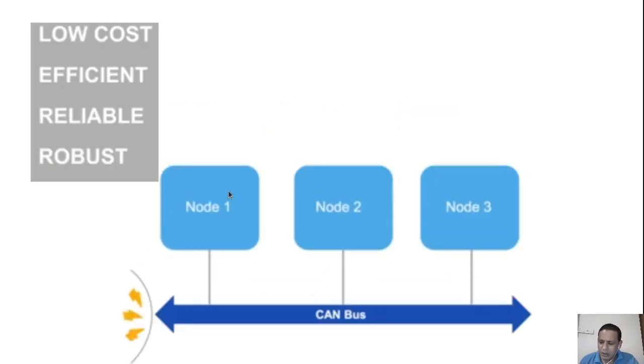And again, this CAN bus is highly robust also. Even if the devices are situated at different coordinates of the vehicle, there can be a lot of electromagnetic interference, and because of that there may be errors. Those errors can be reduced. That is, the electromagnetic interference can be reduced due to this error correction mechanism, and because of the common mode cancellation, we can reduce the errors.